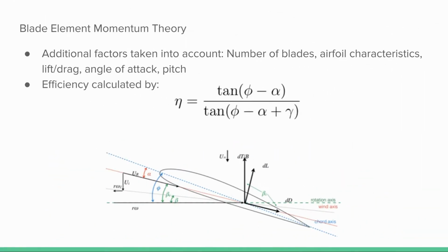The blade element momentum theory builds on both of these and is now applied for the specific case of a propeller. And now this takes into account the number of blades, airfoil characteristics, like lift and drag, which can be obtained for different NACA airfoils using software like Xfoil.